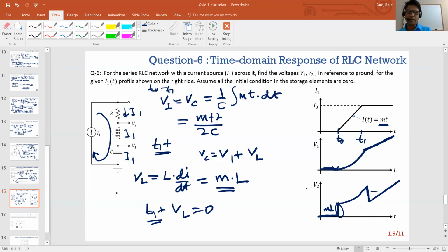So basically there are a couple of elements in this question. I wanted you guys to remember that if you're given an ideal current source, your current is fixed, you just use that current profile. That's it. For every node, use that current profile. And then you just need to know the voltage across capacitors for a given current, or if a voltage is given, you need to know the capacitor current, which are pretty simple. But I have interviewed hundreds of people, and they still get stumbled by this. So just have these fundamentals ingrained. If it doesn't help with circuits, at least it'll help you with your interviews.